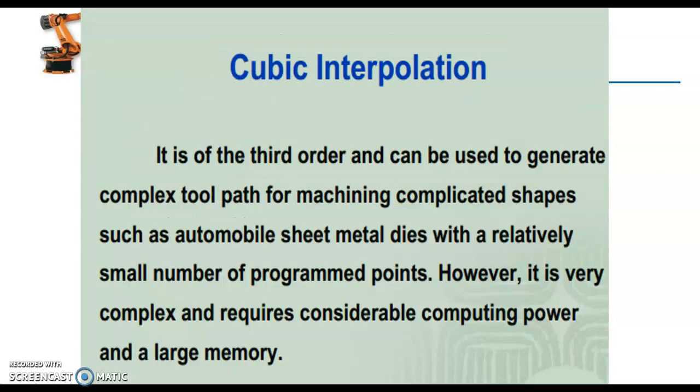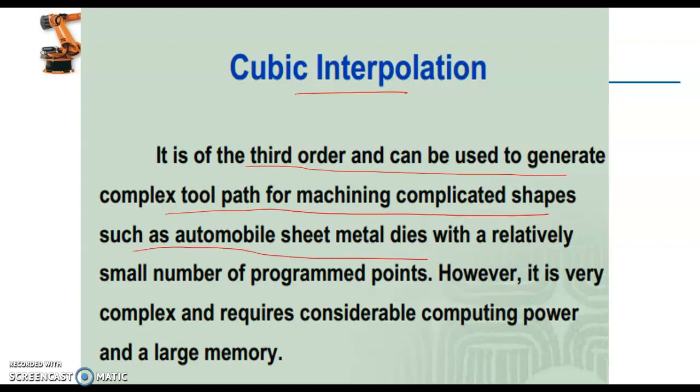And finally, cubic interpolation is of the third order and can be used to generate complex tool paths for machining complicated shapes such as automobile sheet metal dies with a relatively small number of programmed points. However, it is very complex and requires considerable computing power and large memory.